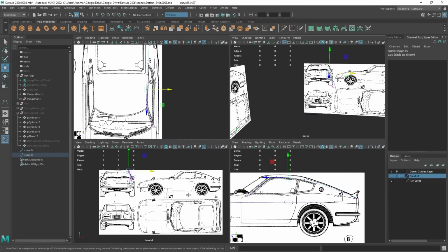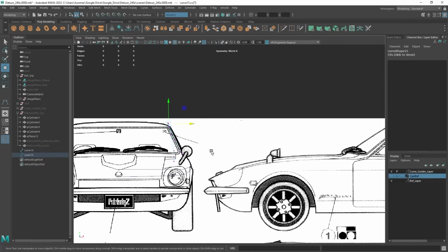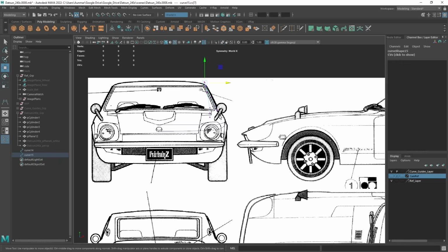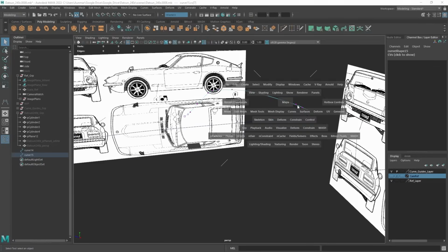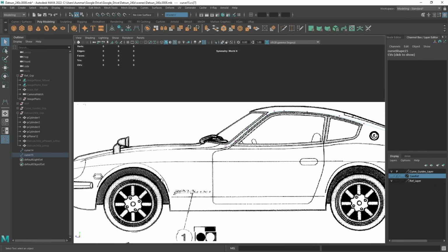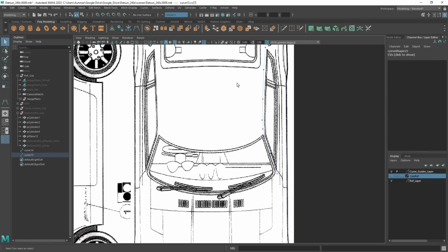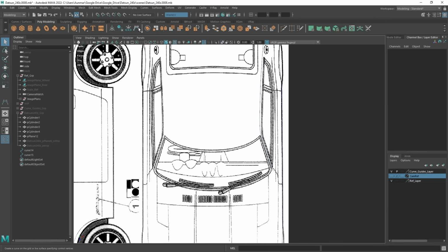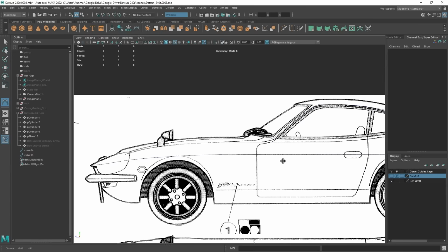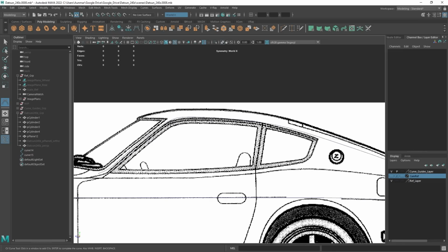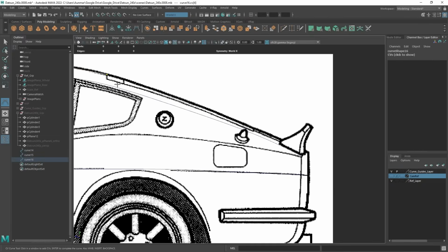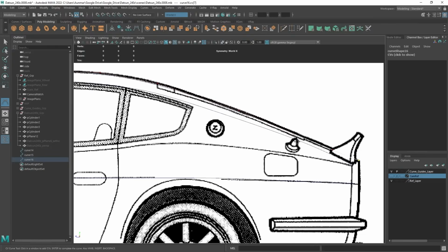And you can see now I'm starting to get this set up and it's looking pretty good. Remember I said the scale on the front is a little bit off, so I may not even use this view. So things are looking good, and I may do just one more, one that's going to simply run down the center of the vehicle. So I'll grab my CV curve tool here, and this time I'm going to do it from the side view again, and I'm going to start up here, and again, the highest point is going to be the dead center. Okay, so you want to do your best to understand exactly where these points are, and you can actually middle mouse drag to move these points, and then left click, and there we go. Hit Q to exit the tool.